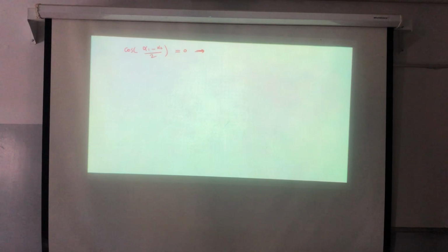I will add here one plus. So I will end up with our magic formula such that alpha 1 equal to pi minus alpha 2. Yeah, good. So now let's see. I'm having two converters connected in anti-parallel configuration. And let's assume that this is the torque and this is the speed. And I need to specify Q1 and Q2. Now, Q1 and Q2 here, which converter is responsible?